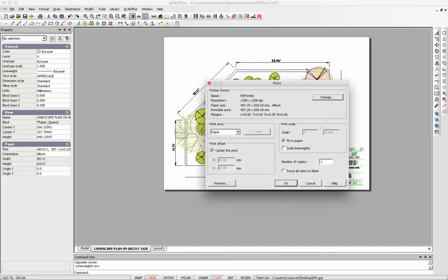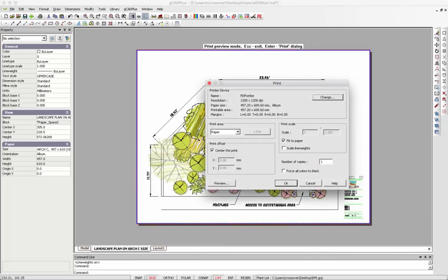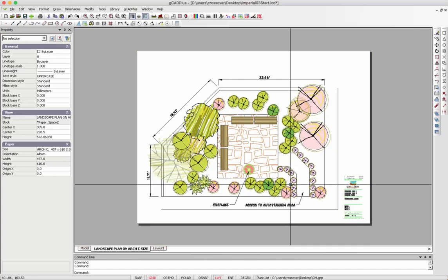So we're going to put it on an A3 piece of paper. It's nearly 1:1, which is exactly what we want, and we could preview it. That looks fine, and we hit our enter key and OK it. So it's now going to produce a proper PDF version of our design at high resolution, and again we'll put it on the desktop and show you the results shortly.